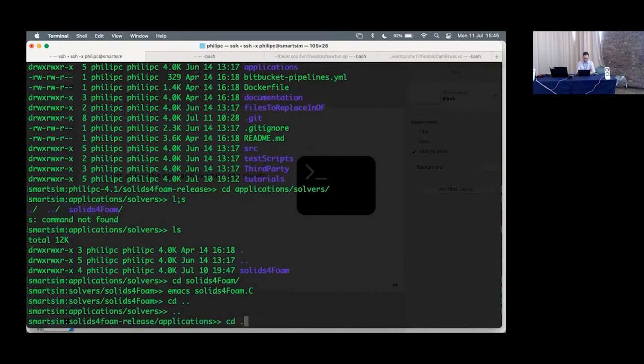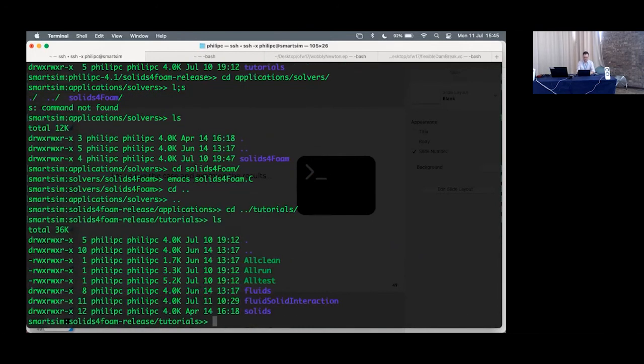Okay, so if I go to tutorials, inside tutorials there are 3 folders: fluids, solids, and fluid-solid interaction. It's not my goal to reproduce all the fluids in OpenFOAM. That would be silly. So it's just the minimal fluids just to show a fluid works on its own, but that's not the purpose of Solids4Foam. So in the next release, there's just pimpleFoam, not icoFoam, pisoFoam, simpleFoam, because they're all a subset of pimpleFoam. You can get the behavior of icoFoam, pisoFoam, and simpleFoam if you just choose your settings for the correctors correctly.